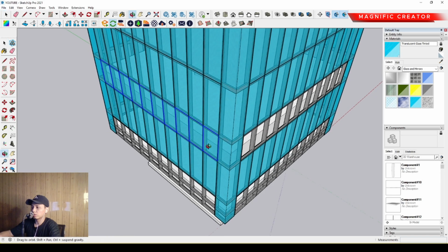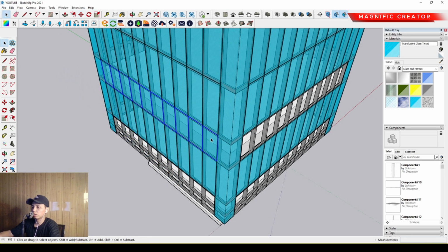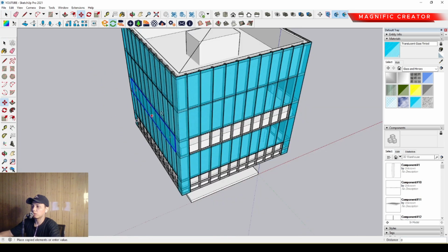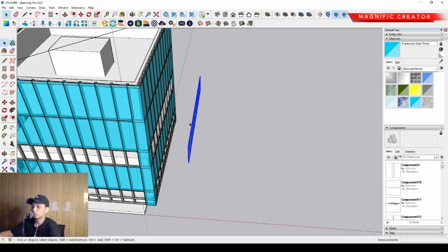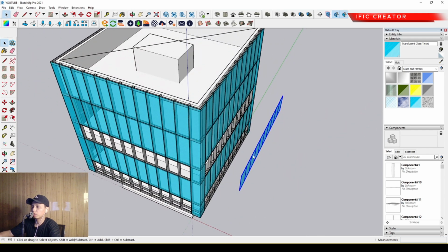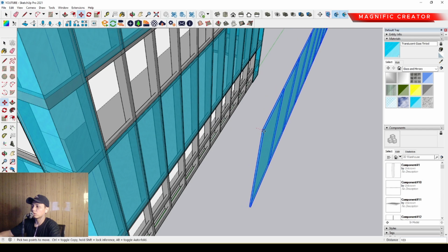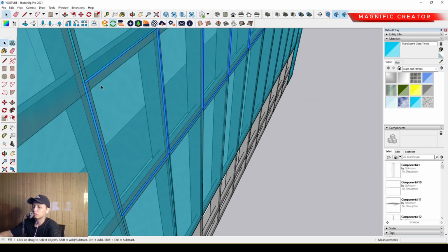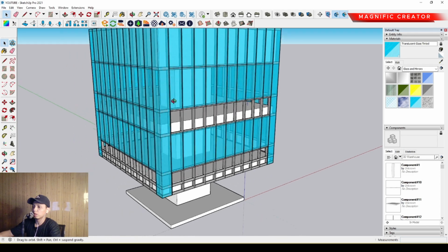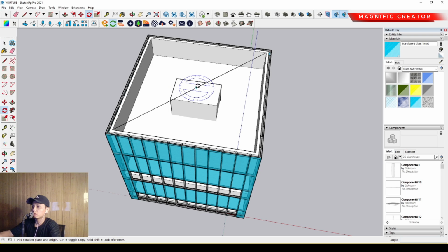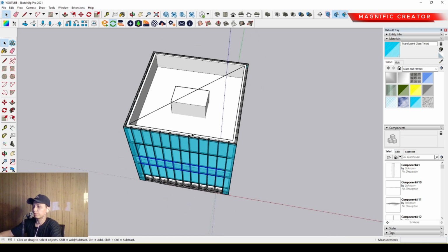Okay, just make a group, and we can check it again. Okay, it's enough. Then we can move to the flip side or another side of the red axis and press Ctrl to duplicate it, and then we can flip it along the red axis. Then we can move and place it in the correct position, and use rotate and duplicate over there, press Ctrl and type 90 enter.